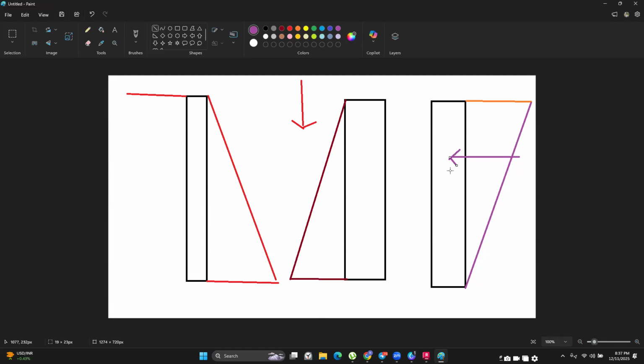If you calculate the moments for this, it will be larger than the moment if this force is at this particular point here, as it should be, because it should be 2/3 from this point of the triangle and a third from the right end of the triangle. So if your load is distributed in such a manner, your force is going to be multiplied by 2/3 the length of the wall, which may be misleading and may lead to an over design. So that's what I want us to avoid.